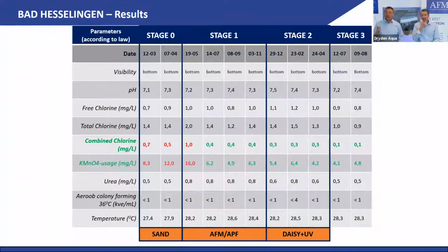Then we started the UV, and clearly you see not really a difference in KMnO4, but a reduction of 25% in the combined chlorine. That's what we said. UV does a good job in the combined chlorine. If you would have used medium pressure, probably that would be 0.2.